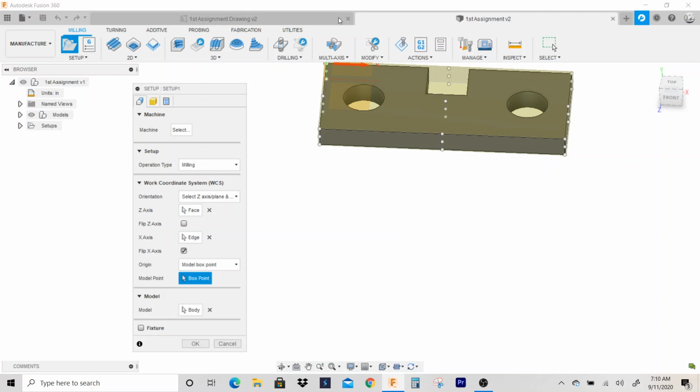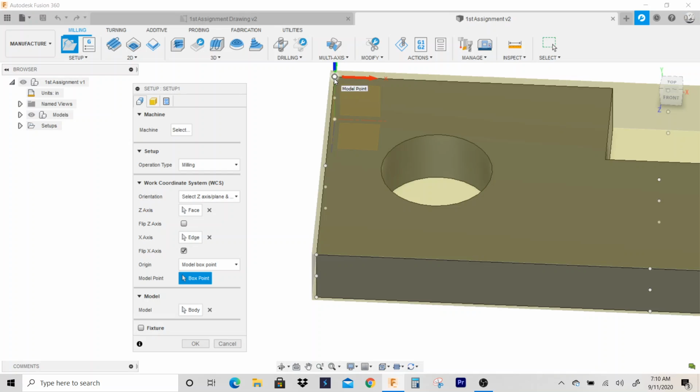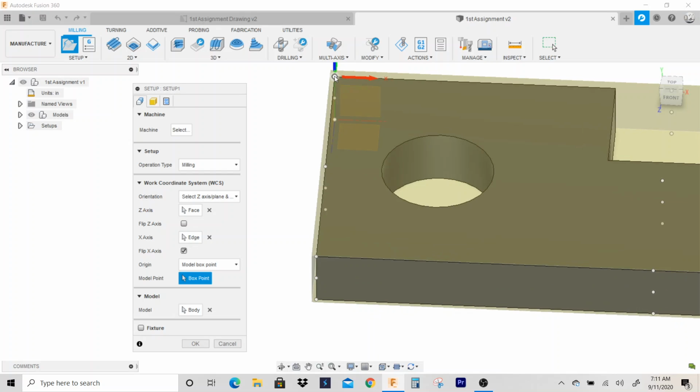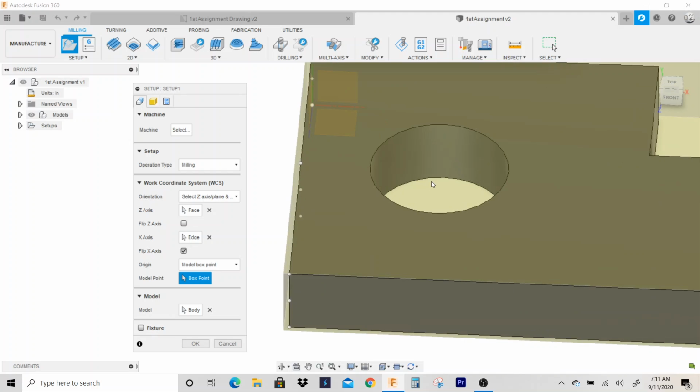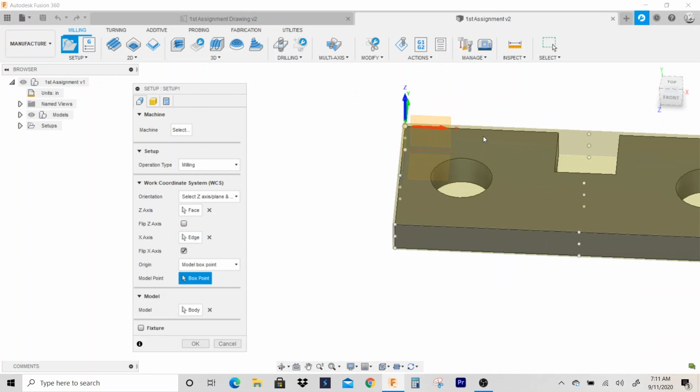Okay, now with it being in the corner up here, I would actually have to subtract down. Okay, because my Y0 is up here, so when I come down, I would come down 1 inch or 1.25. So it'd be Y minus 1, Y minus 1.25, whatever that distance is.